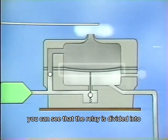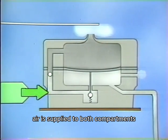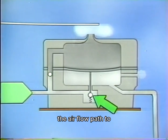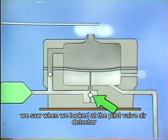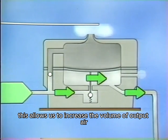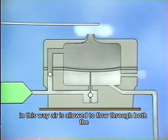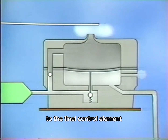You can see that the relay is divided into two compartments by a diaphragm. Air is supplied to both compartments, but the airflow path to the upper compartment includes a restriction that limits the volume of air flowing to the nozzle. The airflow path to the lower compartment has a variable restriction, like the valve plug we saw when we looked at the pilot valve error detector. This allows us to increase the volume of output air without increasing airflow volume to the nozzle. In this way, air is allowed to flow through both the fixed restriction to the nozzle and the variable restriction to the final control element.